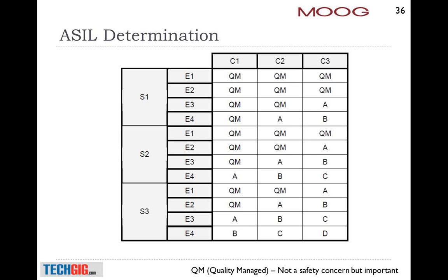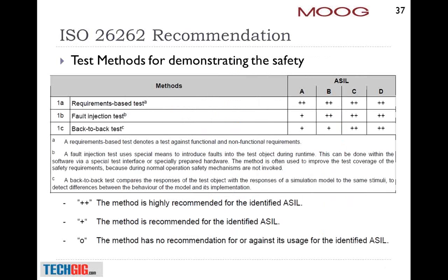And based on these things, you define your levels. So you define the SL levels based on the probability of occurrence, the severity of the accident, and so that is how the level D is the most catastrophic, which is level A in 178C is level D here.